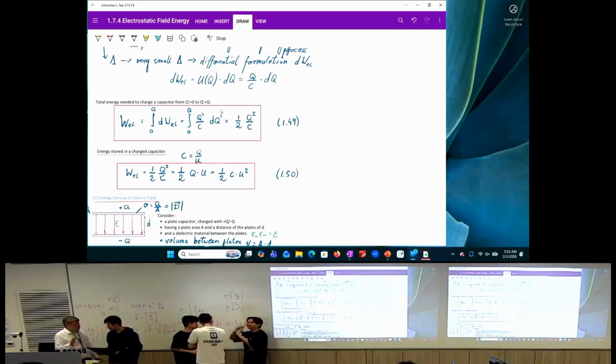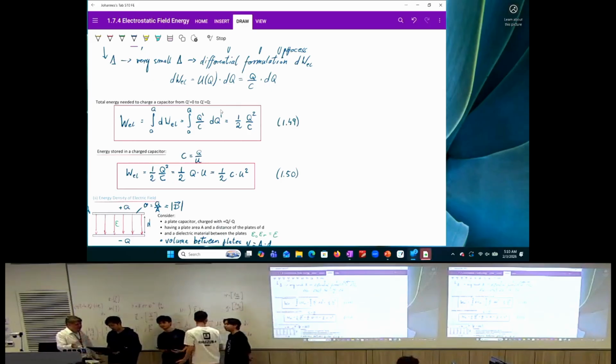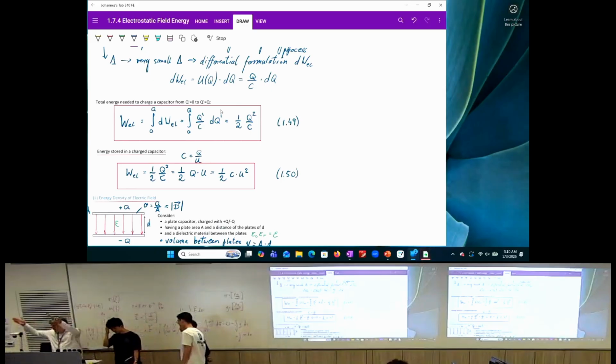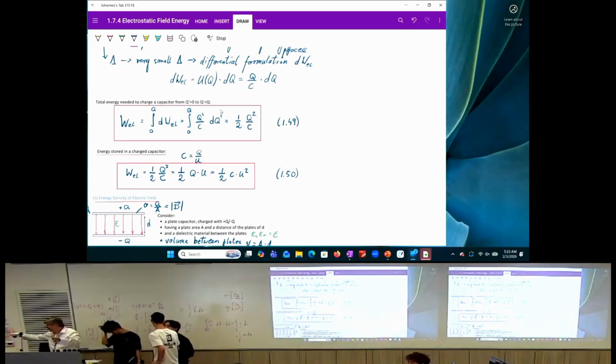But we said, okay, we know the direction. We know already from symmetry. We are just interested at that point in the magnitude, and in the magnitude the minus will drop out. So that's why we wrote just the magnitude of the force and not the full force vector by magnitude and direction. Because we do the direction by inspection, we are just interested in the magnitude, and there the minus does not matter. We can put it in, but because we would take a magnitude on the other side also, it will fall out again.